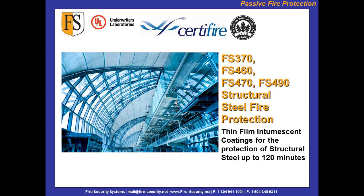The section factor is a very important concept when using passive fire protection on structural steel work. The section factor, or HP/A, is the ratio of the fire exposed perimeter of whatever member it is, whether it's a column or a beam or an I-beam or a square hollow section, rectangular or circular, to the cross-sectional area of the steel. So essentially it is a measure of how quickly the steel section will heat in a fire. So that is your HP/A factor.